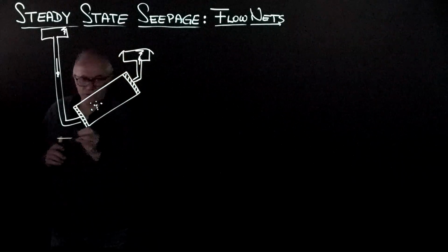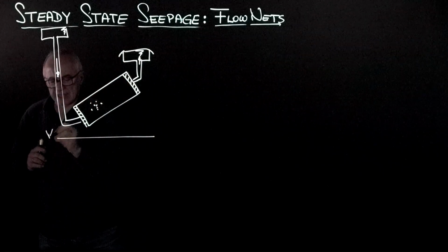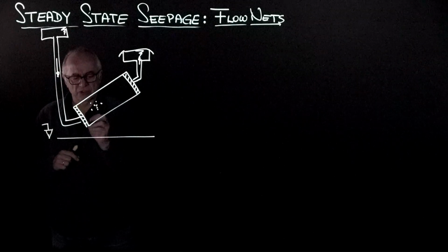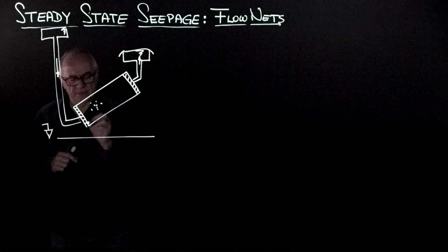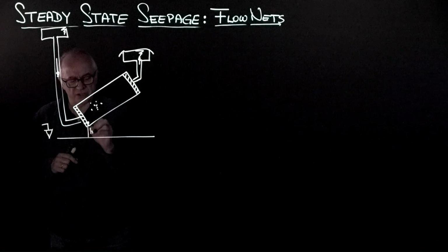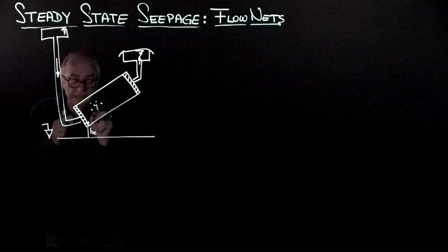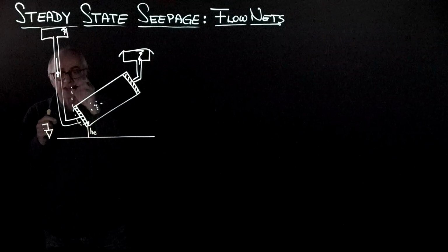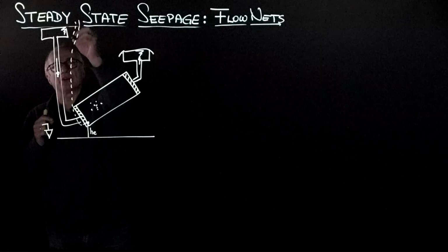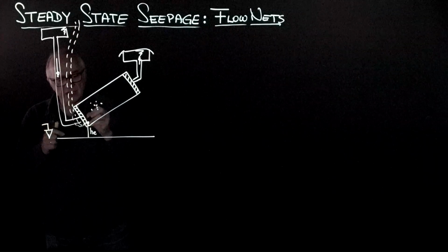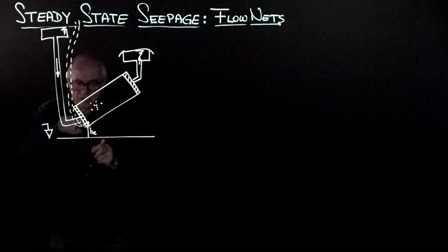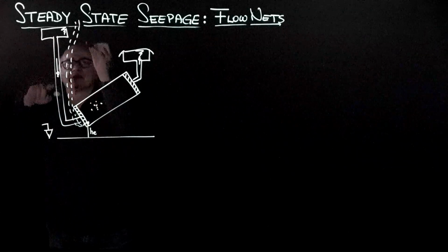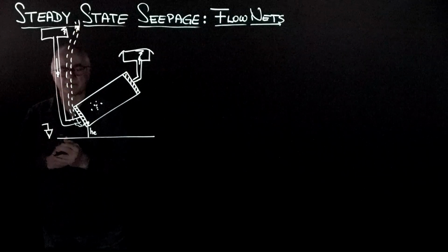But if you are confused at any point, draw the datum. You measure heights with a ruler from that position. So let's say a point here, it has this elevation, and if I place a piezometer here, let's say that is the piezometer, and I bring it all the way to the top, because of communicating tubes between this piezometer across the high permeability stone with this reservoir, the water will go up to the top of this pipe.